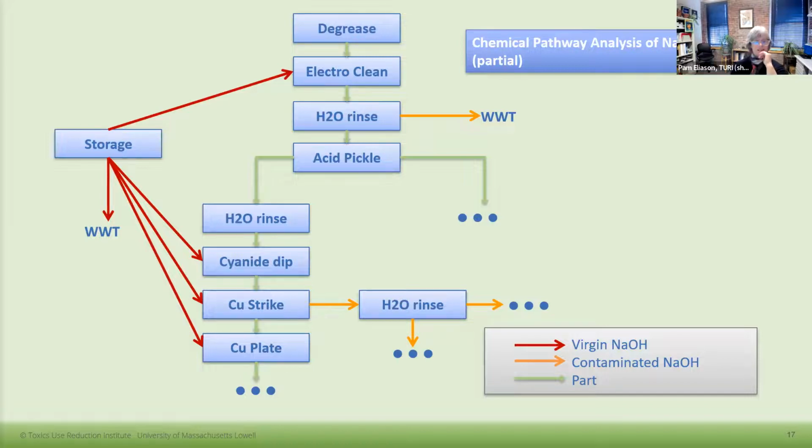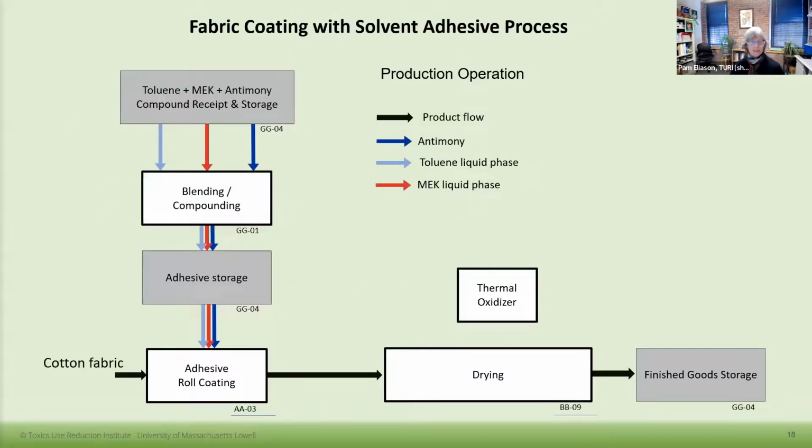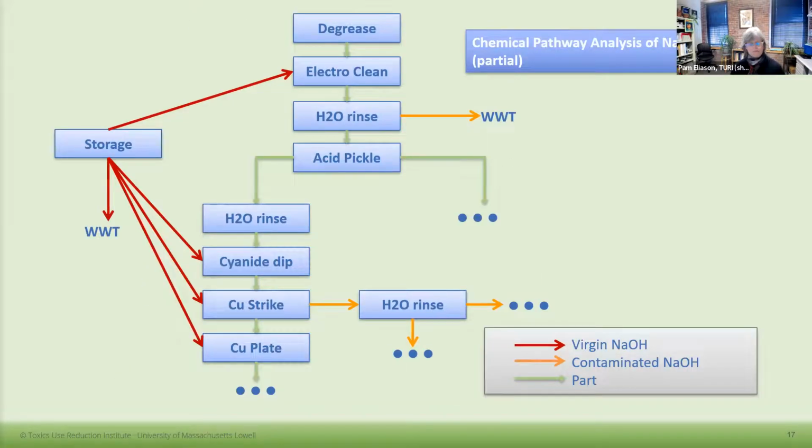Should I be accounting for that? So you see what I'm saying? You can look through each of the process steps and where a chemical is, and you can start to really question yourself. Am I accounting for every aspect of it? Do I have fugitive air emissions in any of these processes that I haven't already identified? So this is what we're using our process flow diagrams for.